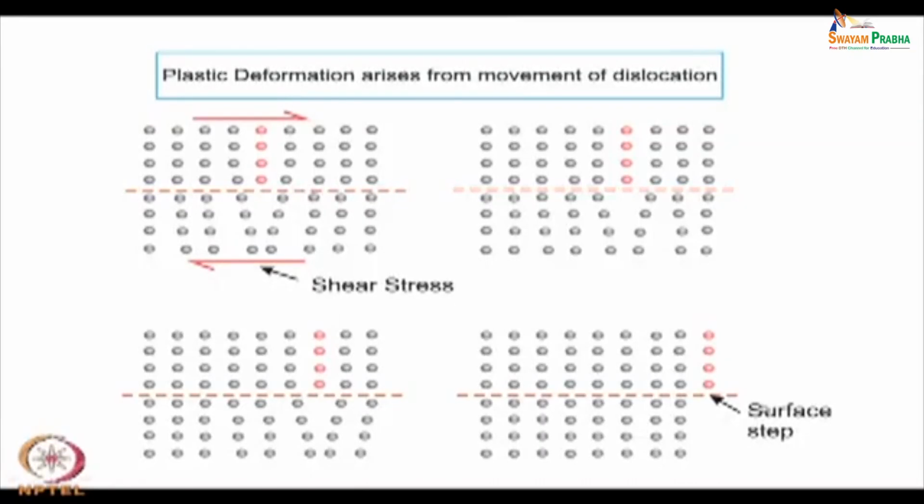So, if you apply temperature, you are supplying an activation energy. The stress likes to be released, so the dislocation starts moving, and as the dislocation goes out of the crystal, the stress is released, okay, at the expense of forming a step. It is generating a deformation, resulting in a physical deformation. So, as more and more physical deformation takes place, the dislocation density may be reduced. Okay.